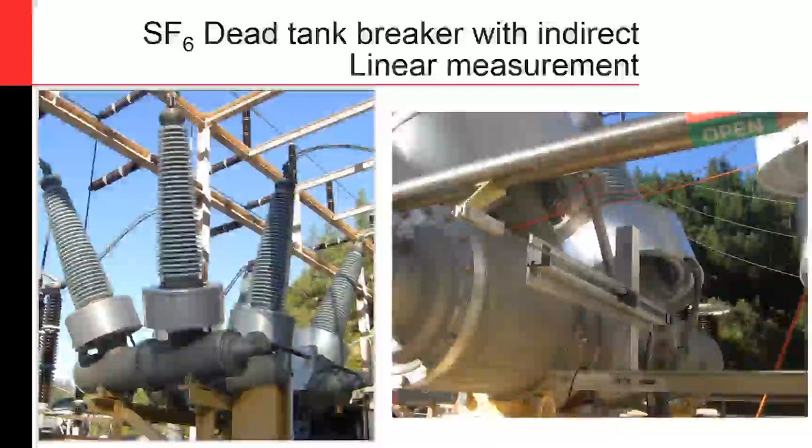Looking over at an SF6 dead tank circuit breaker, you'll see here that it's an indirect linear measurement. So now we have this gang-operated three-phase breaker, one break per phase. And now, if you look on the right, you'll see there's a little clevis that is actually attached to the main shaft that drives all three interrupters.